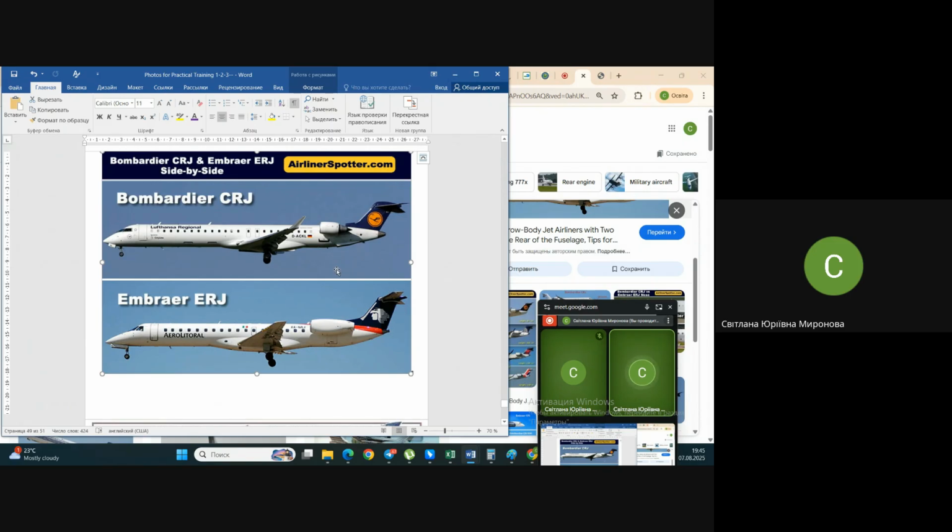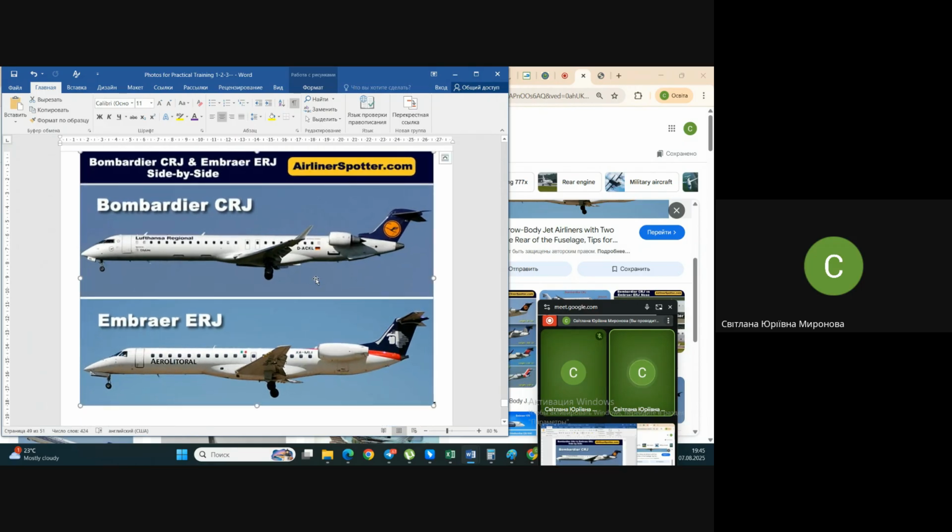What is the difference? Do forgive me this laugh, but pay attention to where the turbofan engine is used. On Mach numbers, as we agreed, 0.6, 0.7, let it be 0.8, but not higher. Higher, you have something like a turbojet with afterburner, not for passengers, of course, no afterburning for a passenger airplane, you understand.